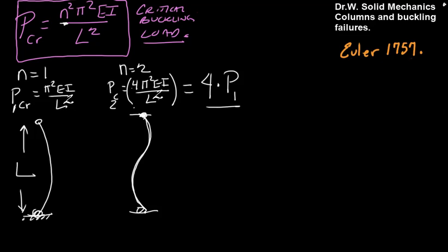However, what if we were trying to reinforce this column because we knew it could potentially have problems here in the middle? We reinforced the column, it would be inducing it to have an n equal to 2 type failure, in which case it would buckle like that. Now, interestingly enough, we could say this top half looks just like my original beam model did.